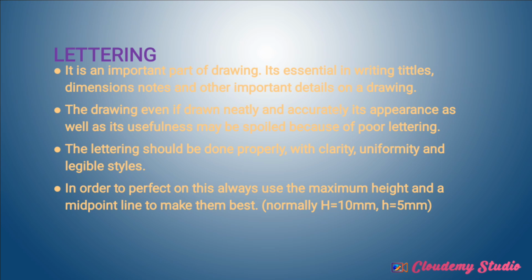If someone is very far away from the drawing, you should be able to see that this is capital C, this is capital D. That is clarity. Then uniformity: the letters should have a uniform size. The letters should not be such that some are big and others are small, or some are straight and others are slanting. Then it means you are poor in lettering.